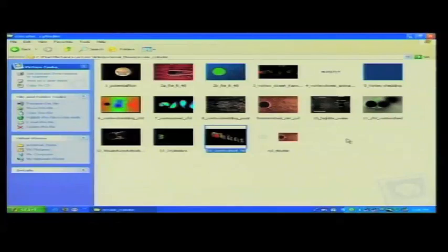So you see this is a 3-dimensional structure. Here the vortex shedding phenomenon is shown in 3 dimensions, but the basic phenomenon is very similar to the 2-dimensional flow visualization observation that we have seen. Now the vortex shedding frequencies are very critical for the design of, say, a structural system, and it may be possible that there is a wide range of Reynolds number to which the flow is subjected.